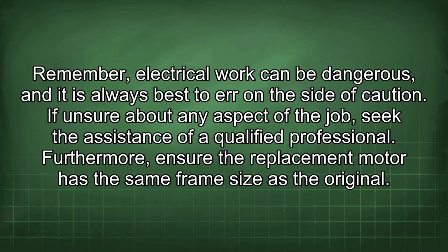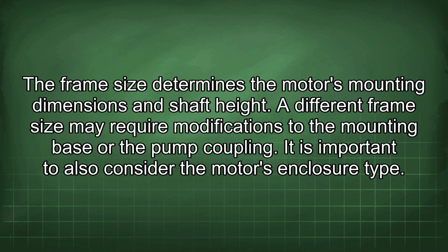Furthermore, ensure the replacement motor has the same frame size as the original. The frame size determines the motor's mounting dimensions and shaft height. A different frame size may require modifications to the mounting base or the pump coupling.